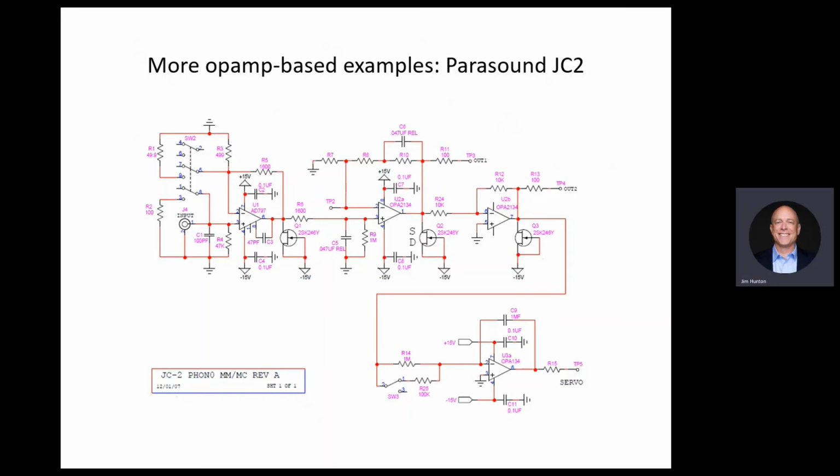In this case, there's no output capacitor because the output is sampled and goes into a DC servo, which we'll not talk about, and it returns somewhere in there to cancel. So essentially you're sampling the output, seeing how much DC is on it, and returning a correction to move that DC to 0. And you avoid putting a capacitor on the output.